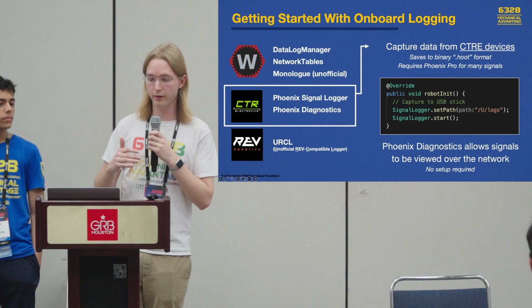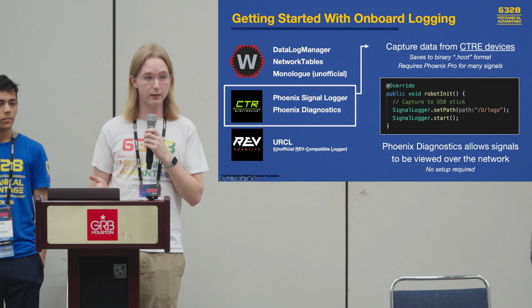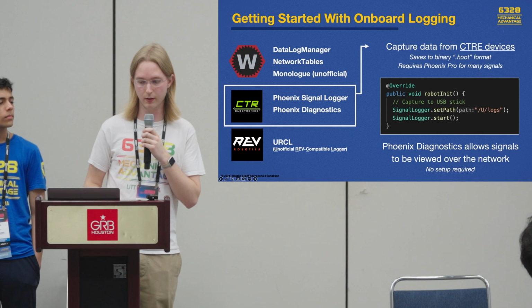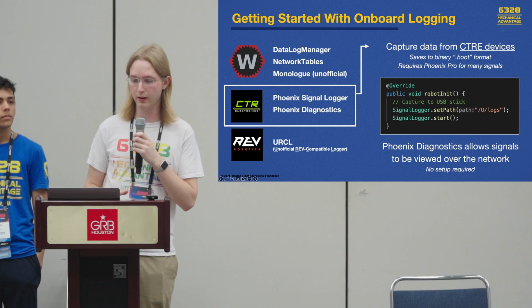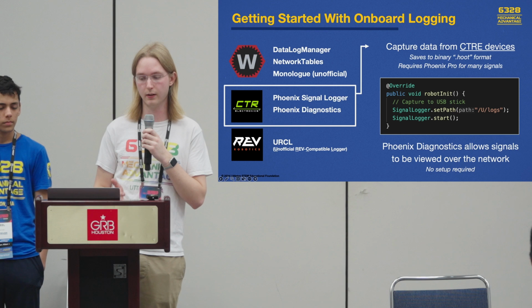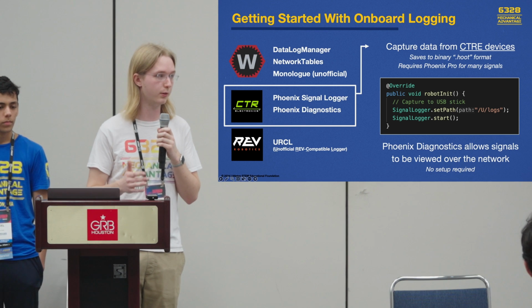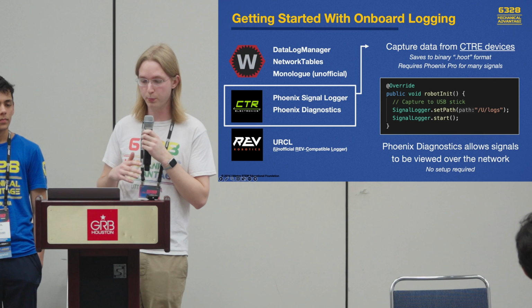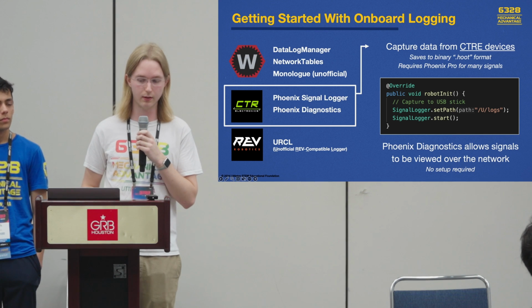Now, this year, there are also several options for logging data directly from vendor devices. For 2024, CTRE introduced their Signal Logger for Phoenix, which captures data from some of their devices to a log file on the Rio. Those devices include the Talon FX, Pigeon 2, and CANcoder. The Signal Logger is super easy to set up.